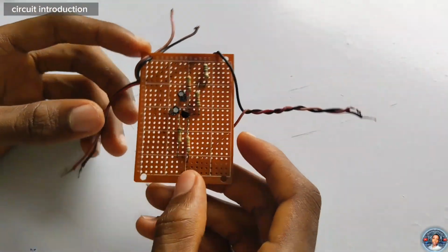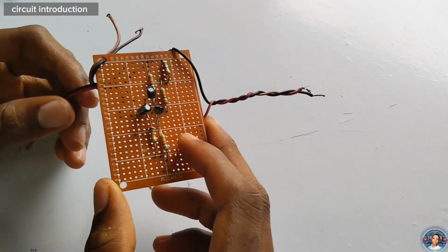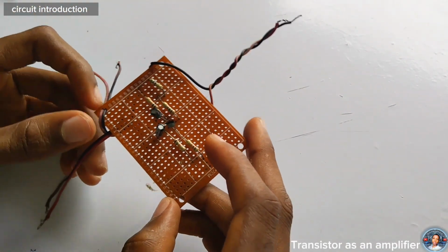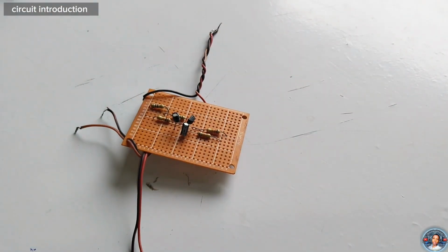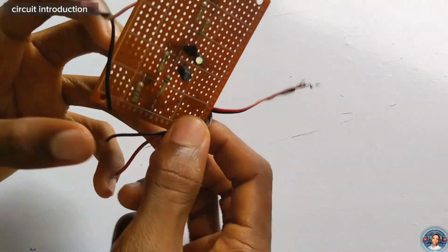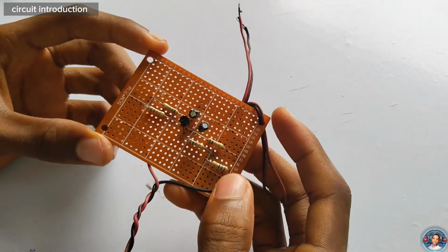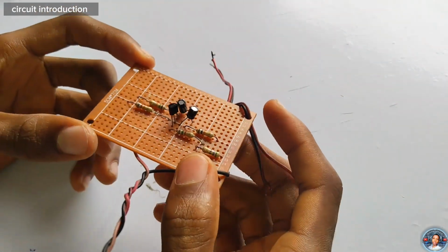Okay, now welcome back. Now this is the preamplifier, making the transistor work as an amplifier. I didn't connect the circuitry on the breadboard, because the breadboard and jumper wire connections normally make a lot of noise and give a lot of white noise at the output of the speaker. So I decided to solder it on a veroboard, which took me half an hour, and it also assembles everything very well in place so that I get less noise at the output of the speaker and a very good project.